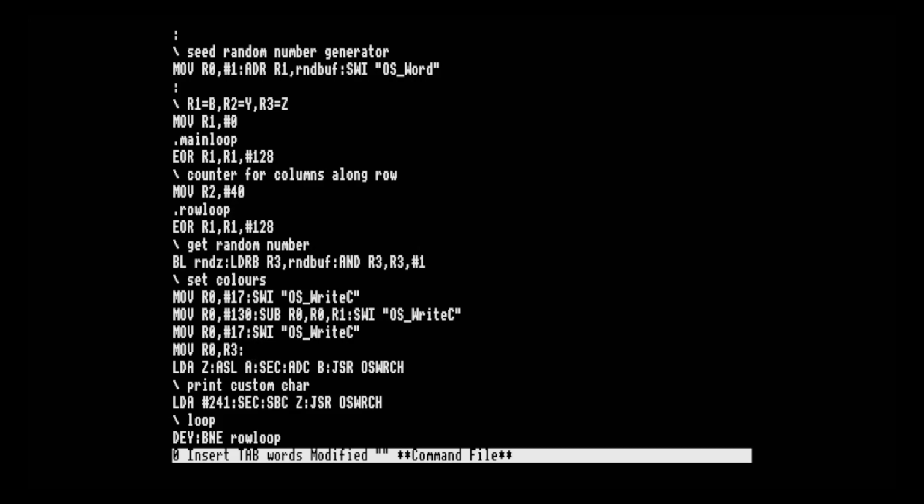Then I need to shift it left by 1 bit. So I'm going to do move R0, R0, logical shift left by 1 bit, which will work, except as I explained earlier, you can use the barrel shifter on any instruction, so there's no particular reason to do this like this when the instruction before is just moving R3 into R0, because we can combine these two and just say, well, I want to move R3, left shift it by 1 bit and store the result in R0, can do that all in one instruction.